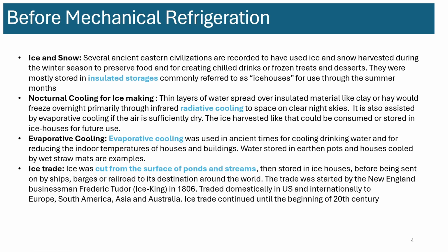The first one, the contact method, what they did was store the ice and snow. In winter, you don't really need cooling inside your house. It's already winter, right? So what you do is you store them for future use. You get the ice and snow and then put them in insulated storages, okay? And if you store a lot of ice inside insulated storages, it can last from winter to the summer and throughout the year, actually.